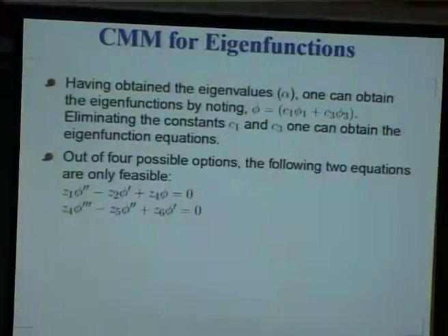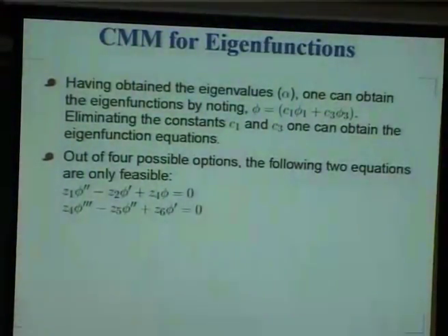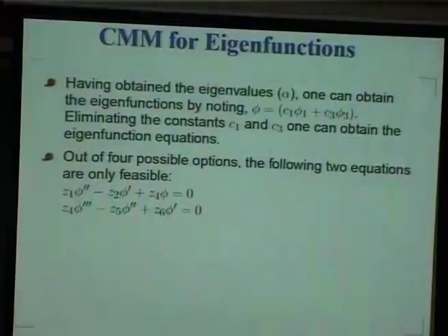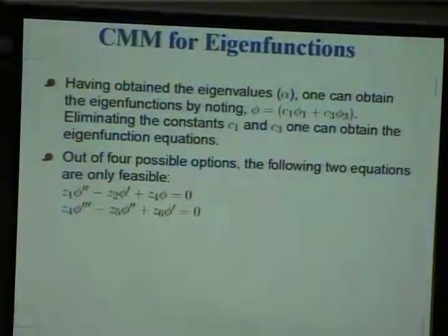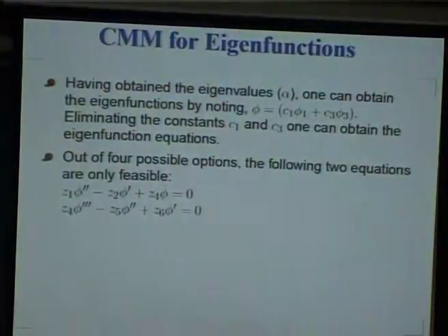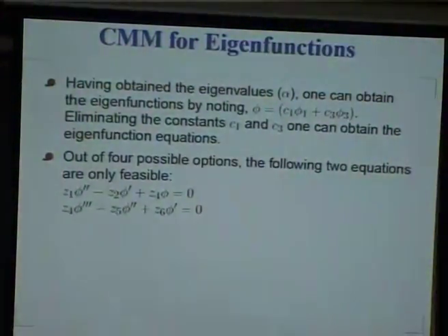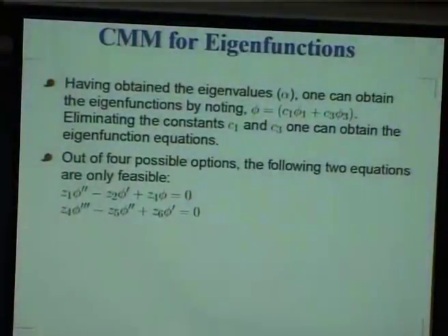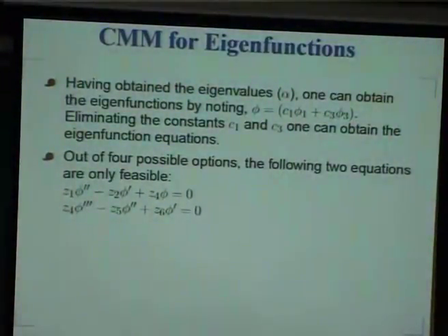I do not wish to get into that part of the story. It is something which we have worked upon, and we have suggested why those 2 equations are not to be trusted. Because you see what happens, our governing equation was a 4th order equation, but there are only 2 admissible solutions. If I look at the first equation, it is a 2nd order equation, so it has 2 modes, and it happens that those 2 modes are the ones that we have retained.